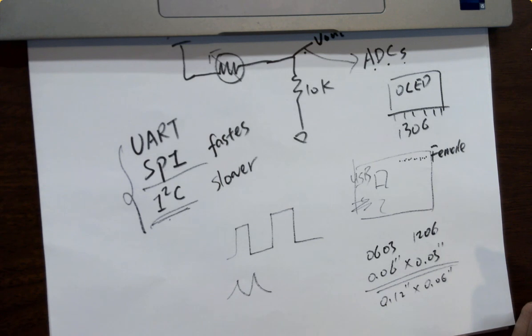I believe in Eagle, you can export DFM check settings. So it might be helpful to set up your DFM check to follow JLC PCB's guidelines, and then have everyone import it and run the DFM check. Oh, you mean for the problems popped up by them, to avoid some of them before sending them off? Oh, I haven't done that before. Good to look into that.